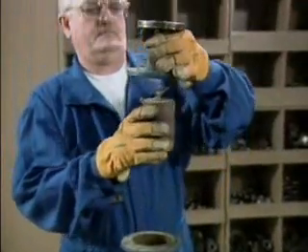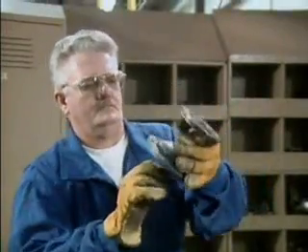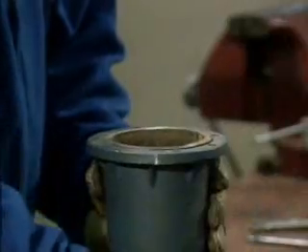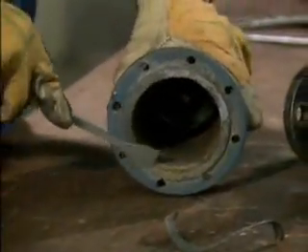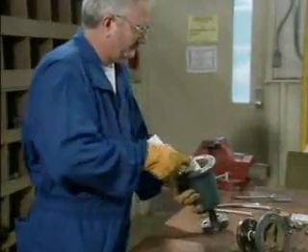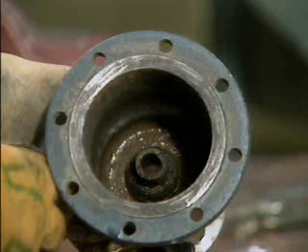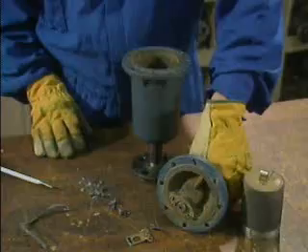Unbolt the cap, then remove it, along with the operating mechanism and the bucket, which are attached to the inside of the cap. Remove the old gasket and discard it. Clean the gasket sealing surface thoroughly to prepare it for installation of a new gasket. Clean accumulated sediment from the trap body and its passages. Check the body of the trap for corrosion, especially at the inlet and outlet passages. The body of the trap, in our example, is in good condition, so it doesn't need to be replaced.